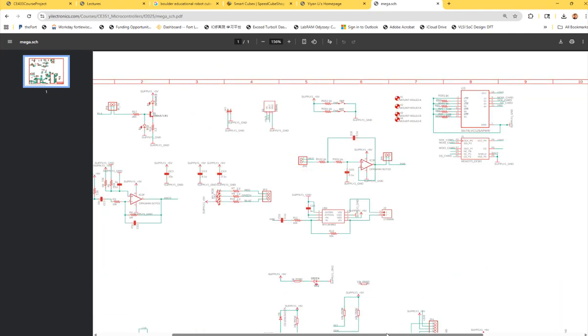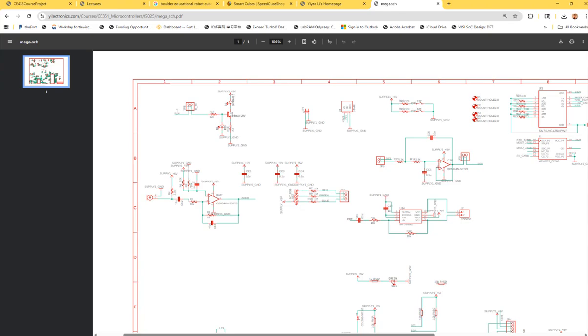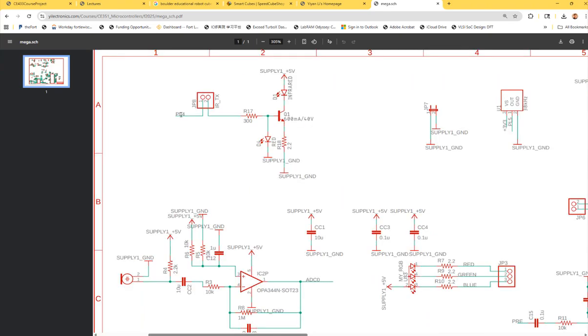However, it's still not working. What you want to probe is the pins over here, because this is 45, and then you probe this point and see if the signal arrives here. You probe 45, it's there, but you probe this jumper here, it isn't. What's the problem? I'm going to design some questions like this on the final exam, okay? I'll give you a lot of debugging problems. So if you probe 45, you get signal. If you probe the jumpers, there's no signal. What's happening?